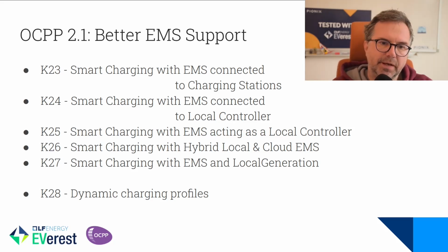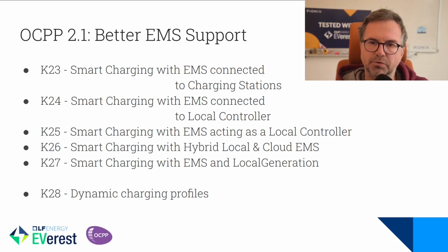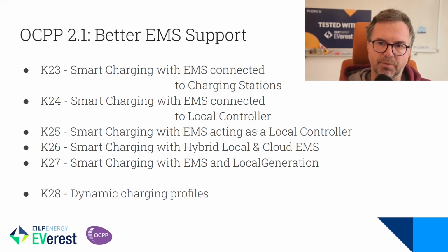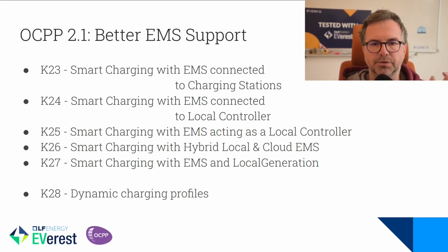On top of that, there's a small new use case as well for any smart charging. It is dynamic charging profiles. Currently, if you have a charging profile installed on a charging station, you can only replace it. So if something changes, you have to replace the entire charging profile. Now with dynamic charging profiles, you can just temporarily update a profile. So you have a charging profile that says what you want to do the entire day, but something changed for 1 hour. You can just set a dynamic charging profile and everything continues after that. So it's a small update to be a bit more flexible on changing profiles.